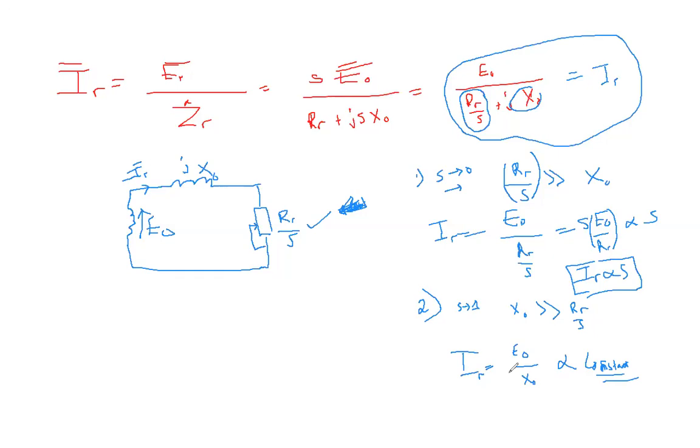It's fine because we know that when the rotor speed is 0, we have the maximum EMF. And then we have the maximum current, which is a constant value, not 0. Okay, that's it with what we have so far. Now with this, you can also see that you can refer quantities, these quantities, onto the stator circuit.